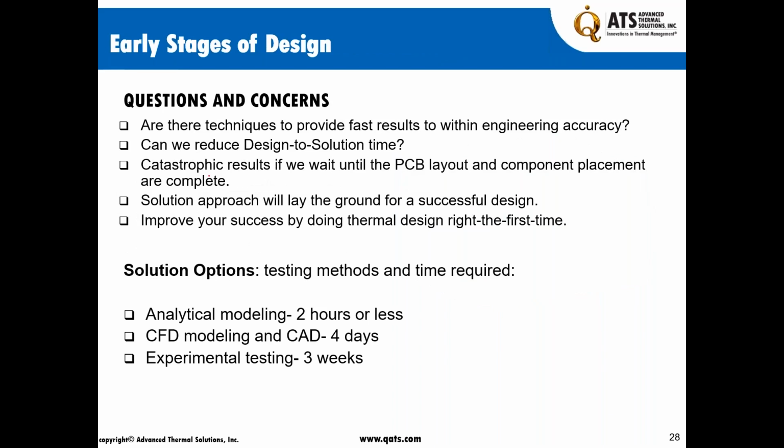The results are catastrophic if we wait until the PCB layout and component placement are complete. I call it catastrophic because if I go through that stage, I have incurred significant costs. We want to do this at the concept stage, when our electrical engineers and system designers have come up with a system, laid it out, and think the board and the system are going to look like this. We want to go through an analysis and give thermal input to the team, versus waiting for the parts to come back. By this time, we've lost time and spent a tremendous amount of money, both soft money and hard money, engineering time and outsourcing for production purposes.